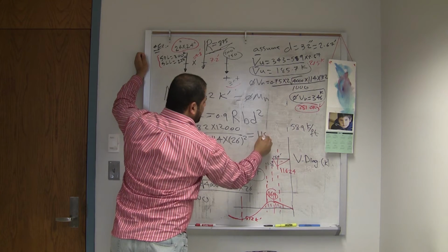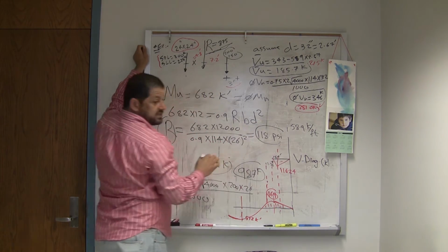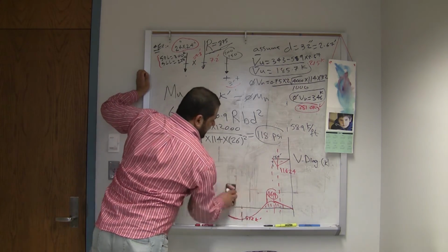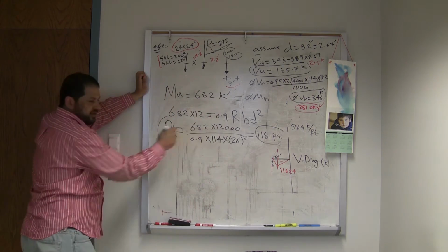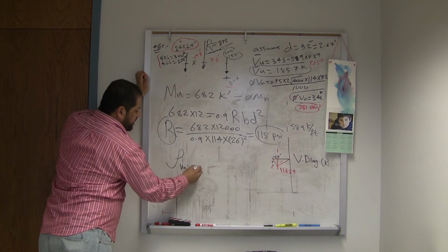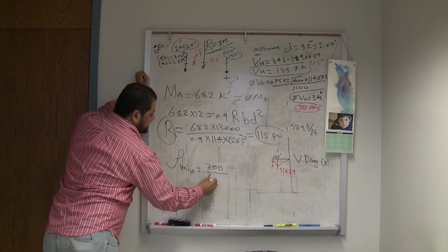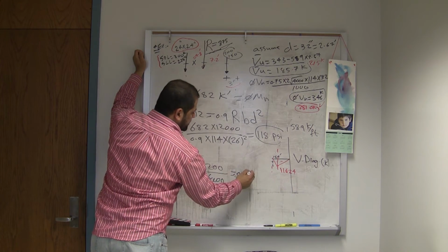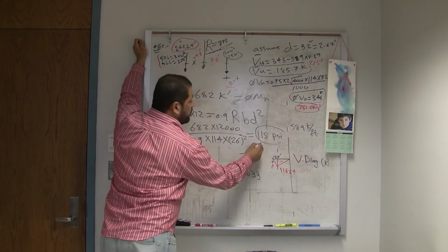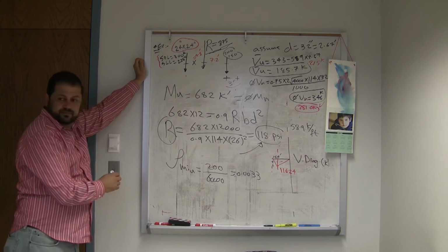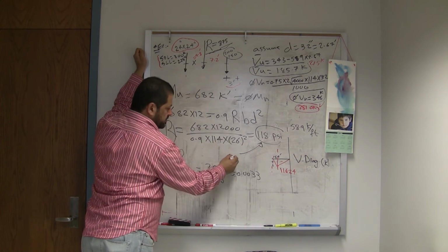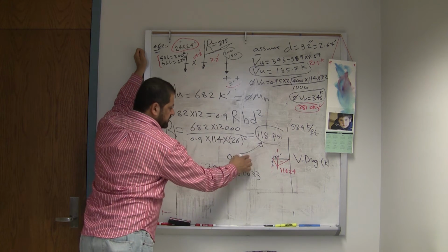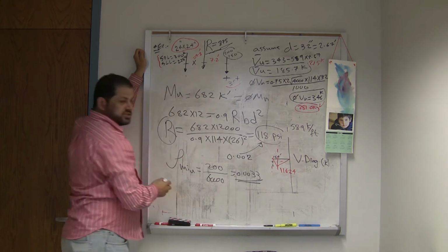118 psi. You go to the design aids, if you want to do it, to calculate the required rho for that. And you will realize that this will be smaller than, I think, rho minimum. Way smaller than that. Rho min equals 200 over fy, 200 over 60,000, which is 0.0033. So for this R from the table, you will find something very small, 0.002. And our rho minimum is 0.0033.